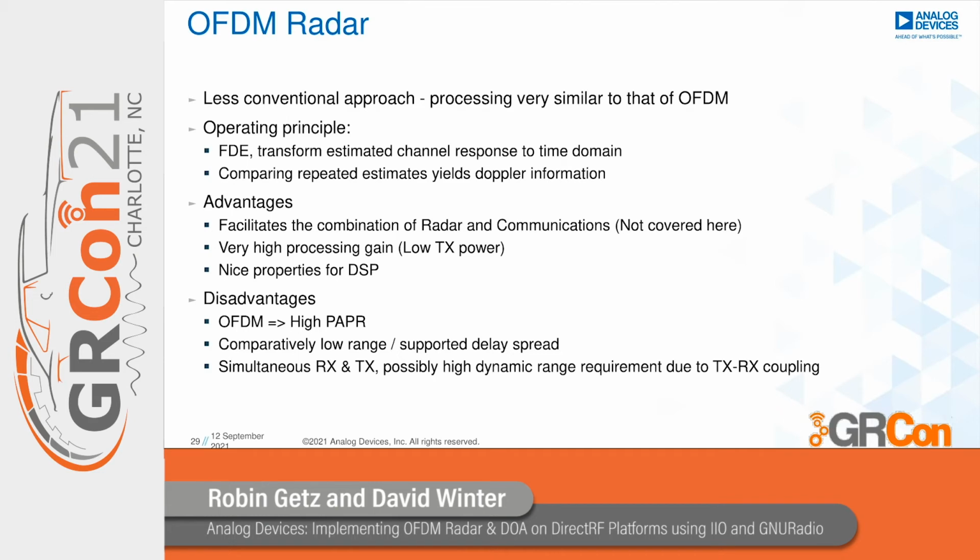So you know your transmit symbols, which are sent to some other device. The frame looks a bit like Wi-Fi because it's just an OFDM frame. Then you send out your signal. The receiver can receive that data, and the transmitter can wait until it gets a reflection from the receiver or whatever you have in your vicinity. And once it gets that reflection back, it can do a channel estimation of its own and get a channel impulse response, and that's basically what we are showing you here in the OFDM radar. That's just a channel impulse response estimation.